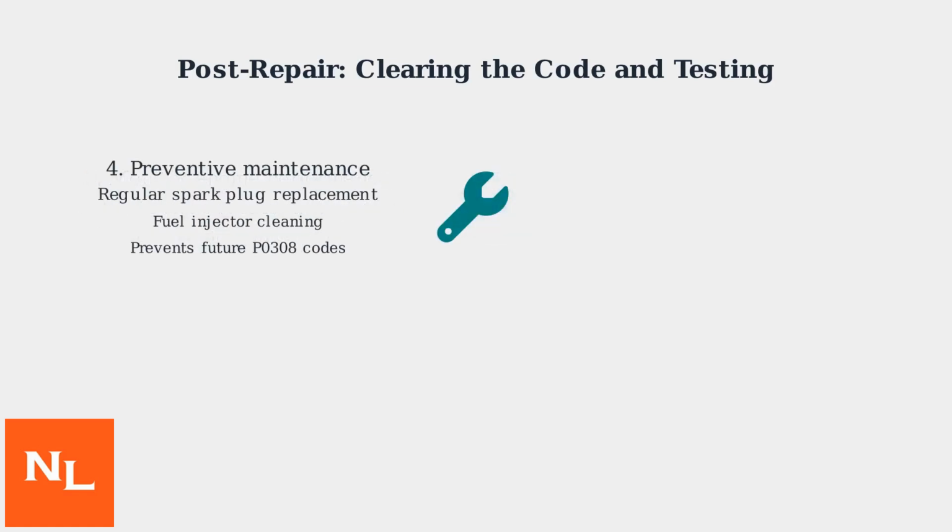To prevent future P0308 codes, implement proactive maintenance, including regular replacement of spark plugs and periodic cleaning of fuel injectors. This helps maintain optimal engine performance.